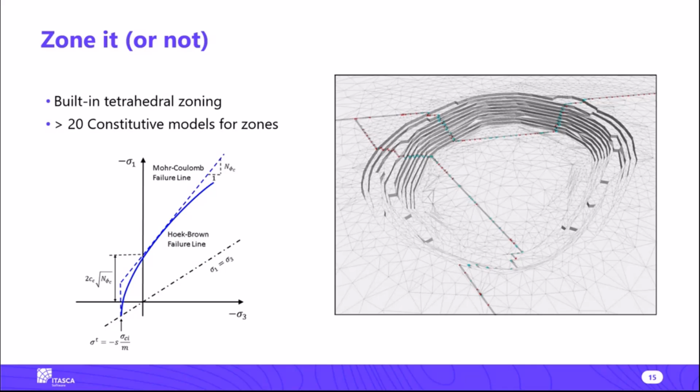In the geological world, more often we have movement on the joints, but we also have deformation of the volume itself, and potentially even failure of the volume itself. So I would say most of the time in these geotechnical type applications, you create your blocks and then you fill them up with zones. And so what you end up with is like a little continuum model inside of each block, which is just a zoned volume.